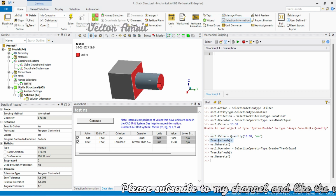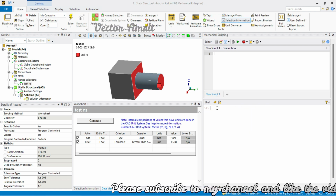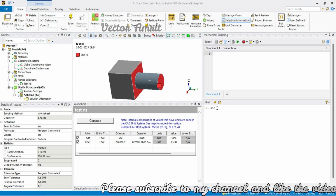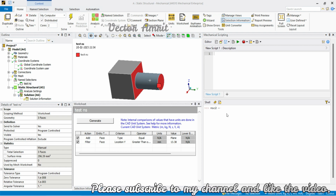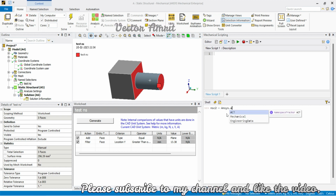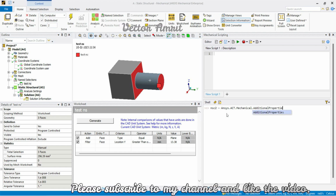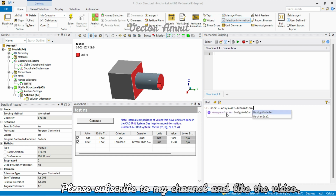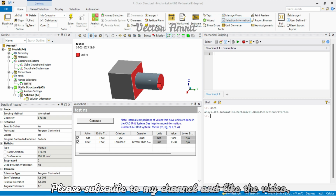So all the name selection criteria that we created were already a part of the name selection. Let's create a name selection criterion independently. So here I will type nsc2. 0 and 1 we already have. So I will make one more independent name selection criterion. Here I have to type ansys.act.mechanical.automation. No, it's act.automation.mechanical, because to remember what it is, you can just type nsc1. So this is what it is.